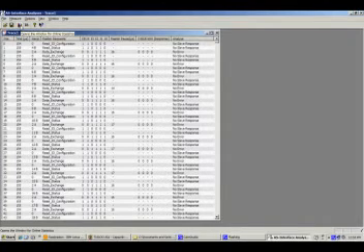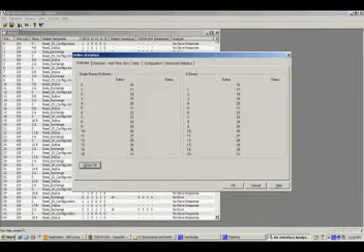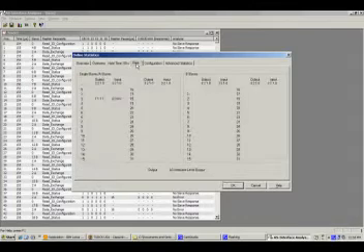You can also go live with this by clicking on this button right here, which opens the windows for online statistics. And if you click on that, you will see that I've actually got just one node here, node 2 on the network. I can go to the overview, hold time here 50 seconds. Go to the data window here. I can actually turn on and off a sensor here and see that particular, on node 2, I've got a